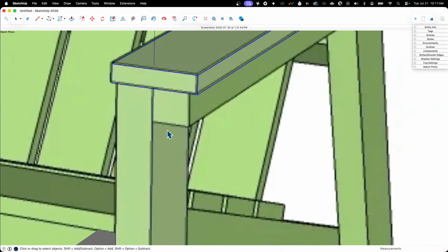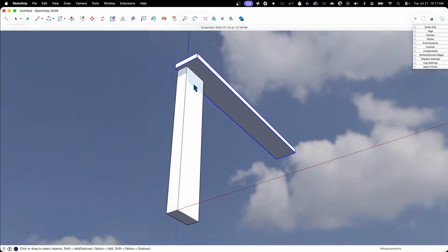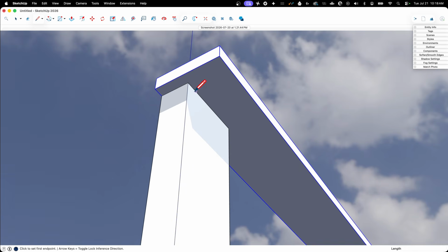All right, next piece, let's put this support underneath here. I'm assuming this is 1.5 inches. So let's see, we'll come across the red axis, hold down Shift. Yeah, it's about 1.5 inches. Now I want this to line up under here, so I'm going to come out of this. I'm going to go right here, come this way, 1.5. I'm going to drop straight down, 1.5.